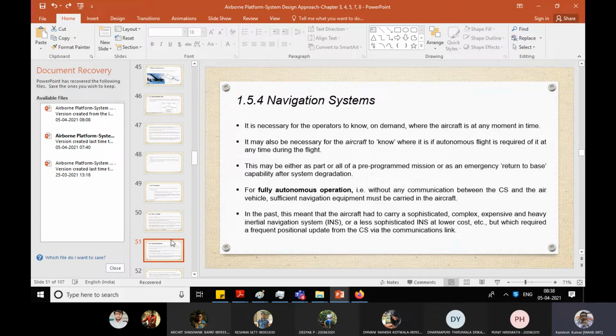So of course GIS is also important when you have a pre-planned mission, because you will see every point on the screen. And then, in other words, your INS system, the inertial navigation system. Long back when I started with the inertial navigation system, they needed a very highly sophisticated INS, because calibration of the inertial navigation system was a very important part. At that time, the GPS receiver was not cheap, so in that case you needed information from the ground to calibrate. Every time you had to calibrate, meaning you should have INS data available through the GCS.